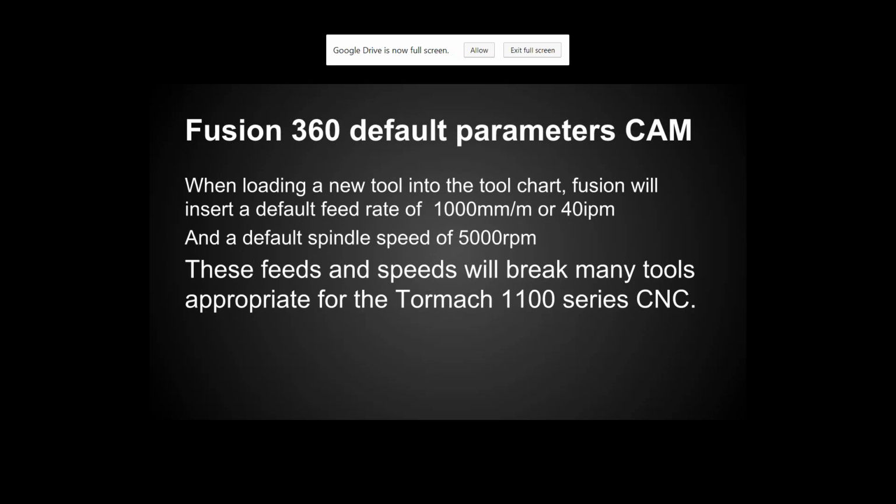These feeds and speeds will snap a majority of tools placed in the machine or crash your part. Running it at 40 inches per minute or a meter per minute is just asking for problems.